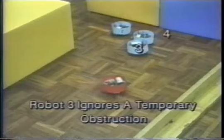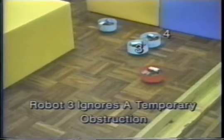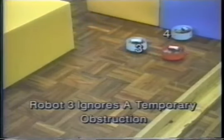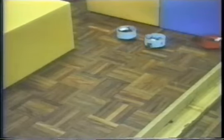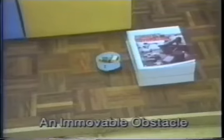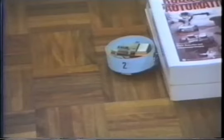In this segment, we see Robot 3, which has been following the trail for some time, being blocked by Robot 4. When Robot 4 gets out of the way, Robot 3 continues tracking the trail. If the obstacle does not move within the timeout time, the robot gives up and looks elsewhere for a trail. While following a heat trail, the robot meets an immovable obstacle blocking its path. After timing out, the robot backs away from the obstacle and goes in search of another heat trail.